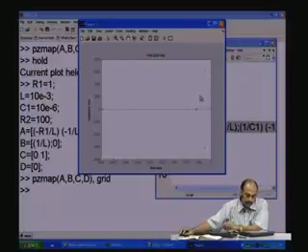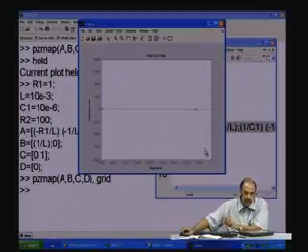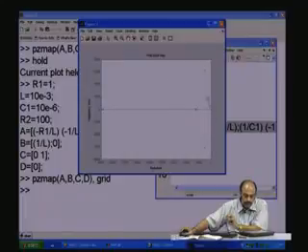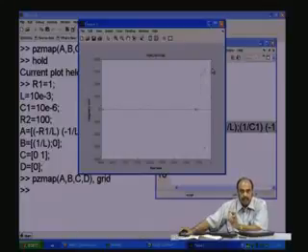So, now let us have a look at the plot. So, you see the plot here. This was the earlier plot on the real axis, and now these two poles, the green ones, are the ones after having changed the parameter R2. So, as R2 starts going towards infinity, these two poles will become complex poles with a mirror. That is why the 180 degrees phase shift, and they gradually start moving towards the imaginary axis, which is this axis, and become more and more oscillatory.